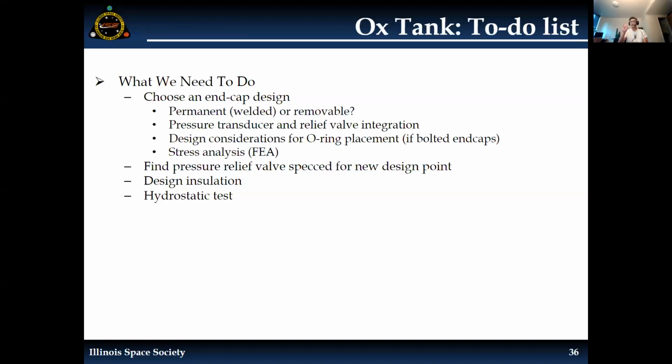So yeah, two different pressures that we're considering. The pressure that we're going to store the nitrox at, and the pressure that we design our tank around. Yes, safety factor is based on the 76 bar, not the 45 bar precisely.